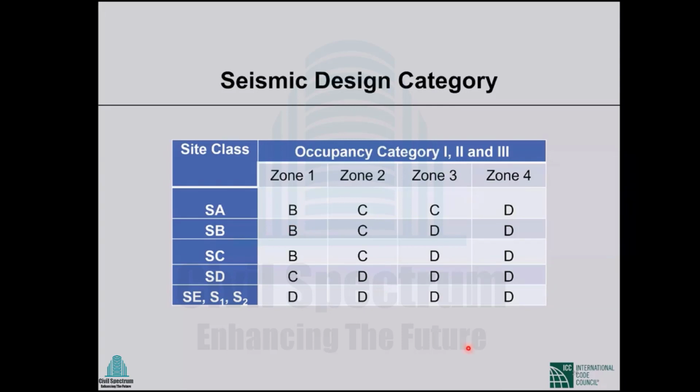there are definitions of seismic design categories B, C, D. Simply saying, ordinary moment frame actually corresponds to SDC B, IMF, intermediate moment frame, corresponds to somewhat zone SDC C, and special moment frames correspond to D. Then you understand that in Sylhet you can never design a structure considering IMF or OMF. The structure must be SMF.